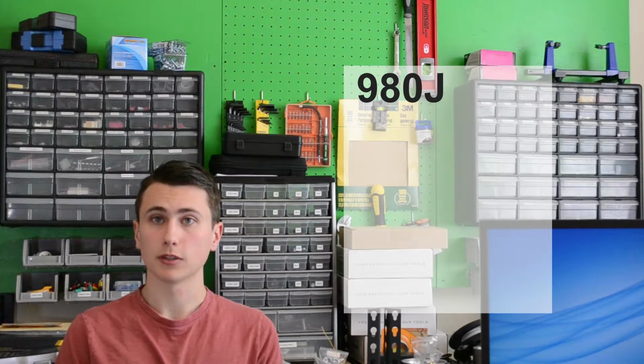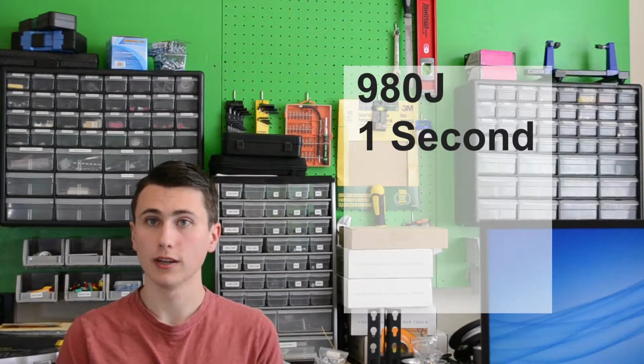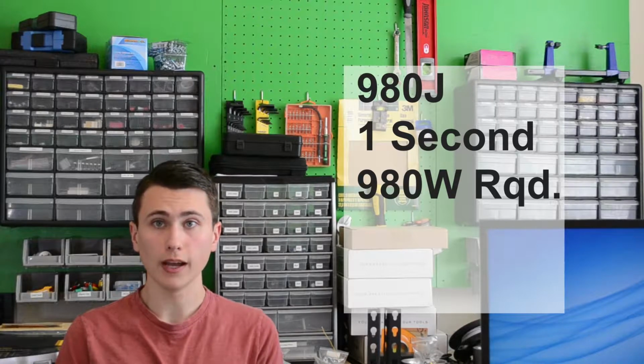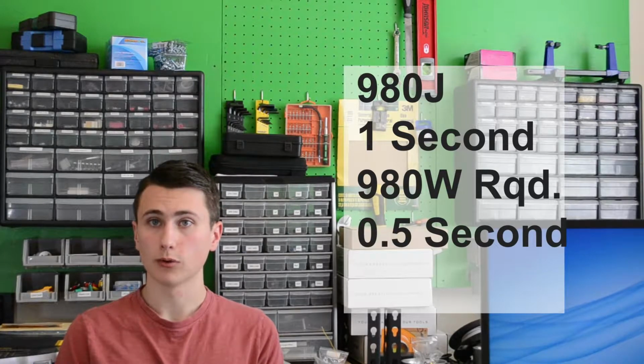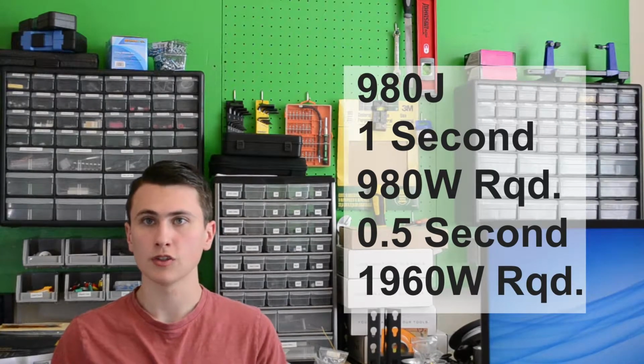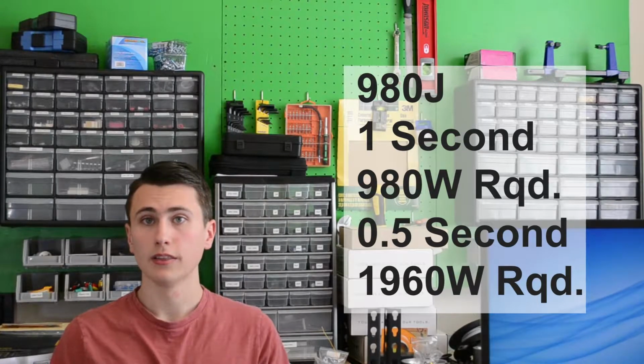If this object must be lifted in 1 second, that means that we need to use a motor that uses at least 980 watts. If that object needs to be lifted in 0.5 seconds, we will need to use a motor that consumes at least 1,960 watts. If that motor is only 80% efficient when converting electrical energy into mechanical energy, then we would need to use a motor rated for 2,352 watts.